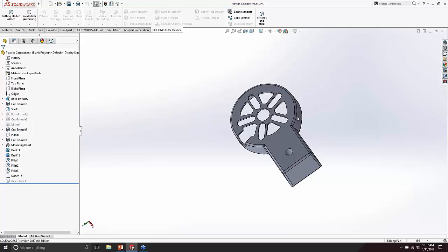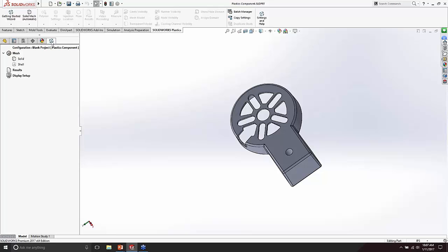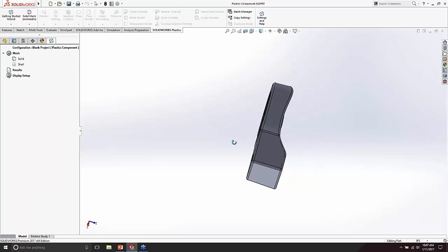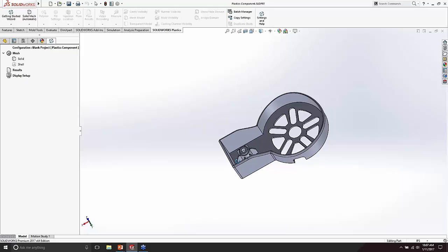So what I'm going to do is start walking through the injection molding process inside of SOLIDWORKS Simulation here for us. With SOLIDWORKS turned on, you can actually enable SOLIDWORKS Plastics. Using SOLIDWORKS Plastics simulation, you'll get a nice little toolbar at the top, which allows me then to access all the simulation tools inside of here. So I'm going to walk through this process.